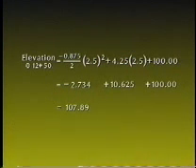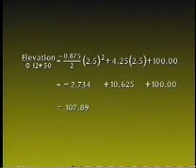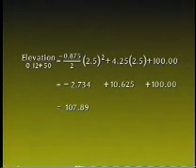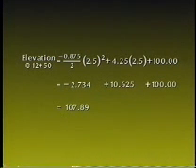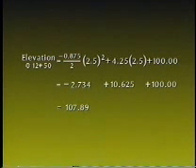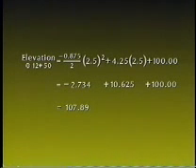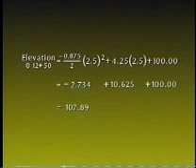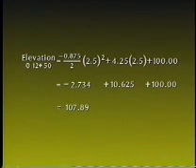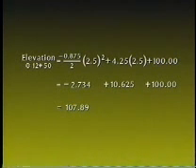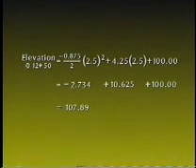For example, let's say the station at the BVC of our curve is 10 plus 00, and the elevation is 100 feet. The elevation at station 12 plus 50 would equal minus 0.875% divided by 2 multiplied by 2.5 squared, plus 4.25 times 2.5, plus 100 feet, which equals 107.89. In practice, it's not always critical to know all the equations.